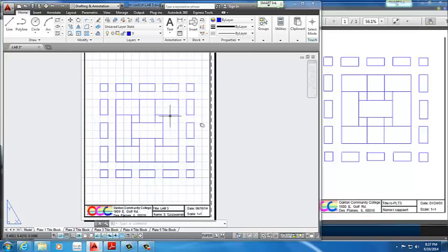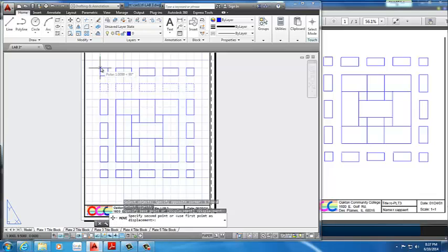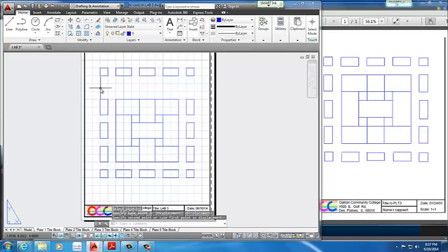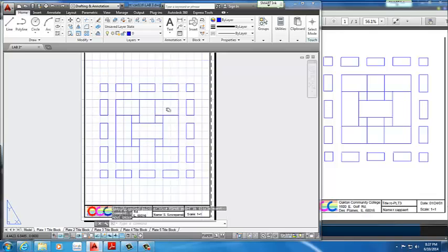So now you have two options, if you feel like going back to your other lab 1 or 2, stretching or moving. Moving is that you have to use the move command, and that's how you would do it. But to stretch a line, you just select the line, select a blue point, and you can stretch it from there. Unless you select the center from where you want to move it from, that's a whole different story. It just moves it. So I want to move it from here. But each end point of a line allows you to stretch it out to make it longer or shorter. And then once you have that done, save your work.